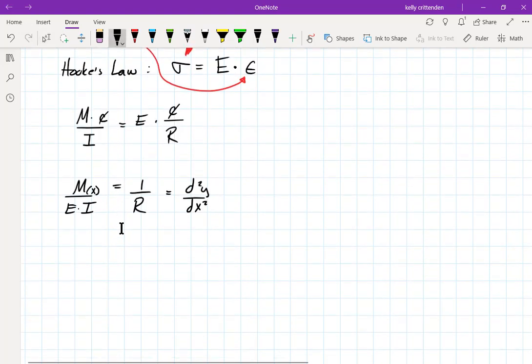So this is a function. The bending moment is not constant in the beam, it's changing. And there are sections in the beam where the equation is constant, but then as soon as you add a point load, or you add a concentrated moment, or you add a distributed load, then that changes the equation m of x. So you would actually have to develop a piecewise function.